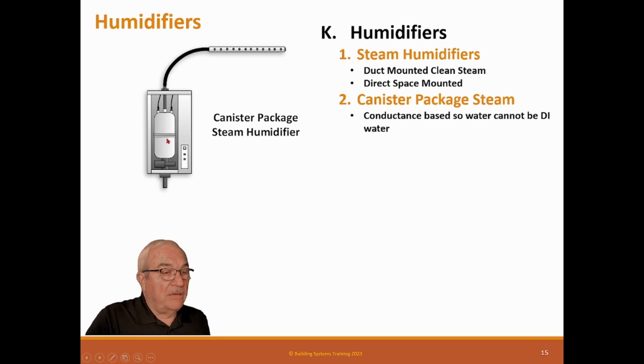I had a client hire me at a big data center, and they were losing them every 3 months, and they had like 10 of them. I said, what can you do? Well, we can run RO water through them. So we put RO water on the incoming water of these units to clean them. Well, they didn't work at all because there were not enough solids in the water to produce the conductance and electricity from the rods in here. So we went back, and I put a TDS controller on it, and had it run at about 50 TDS. I mixed the dirty water with the RO water, and we made these last for 2 or 3 years producing steam. So it was a big win for them.